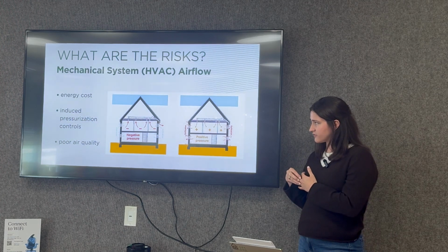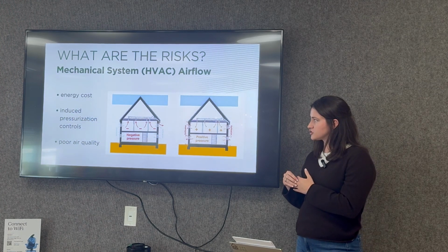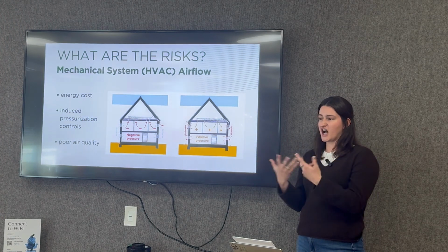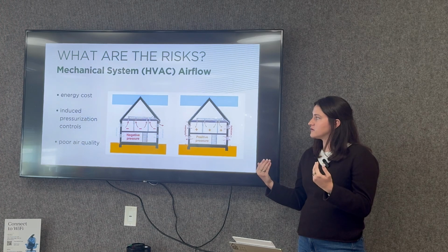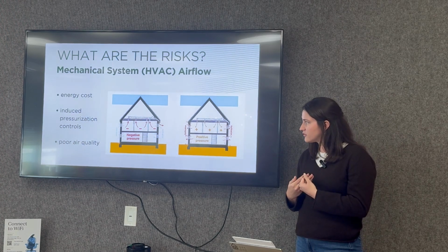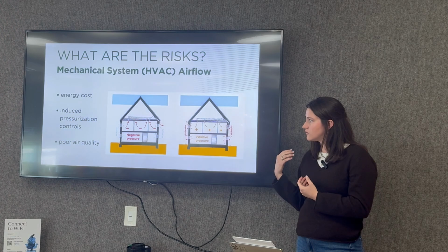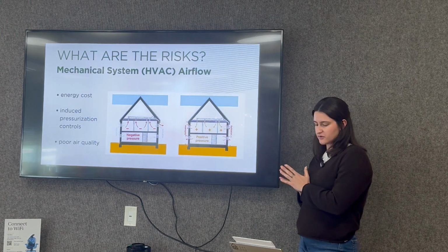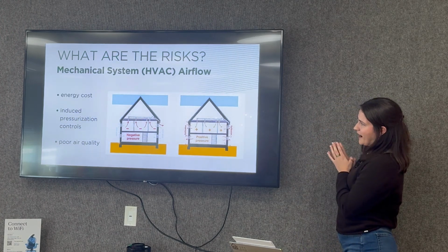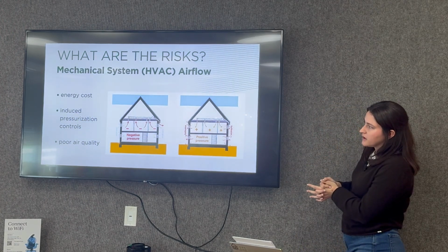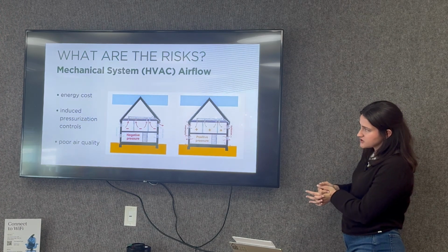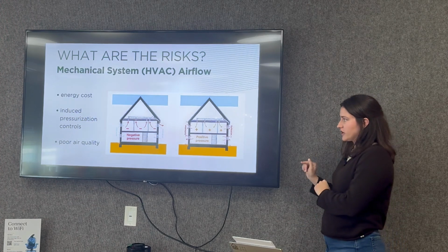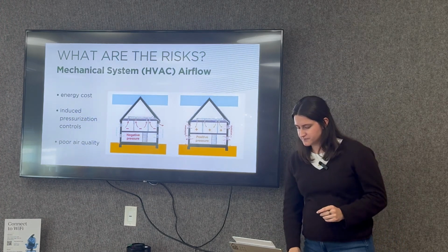When a building is negatively pressurized, you risk drawing in moisture and hot air through deficiencies in your envelope, which can then lead to poor air quality. If you need to pressurize your building intentionally, whether positively in a hospital or lab, or negatively in a really cold climate to avoid the risk of condensation, it'll be easier for you to reach your air leakage targets if your building is more airtight.